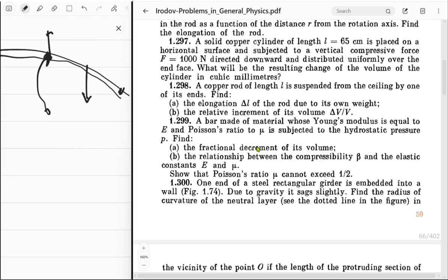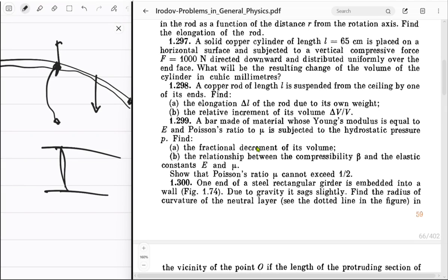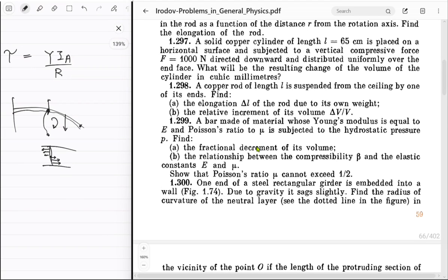The thing is, you have to think of it not as a single point, but as a cross section. So this is how it should be. I know this should be rotated, but think about it as rotating after you get the thing. So it's supposed to be rotated, but just do it. Okay, so this torque is in the clockwise sense. You want an anti-clockwise torque on this piece, right? The way this will actually work is that you will have these normal forces, which will add up to zero because no horizontal force is there, but they will create a torque about this point. Because of that, you will have cancellation of torques, and this won't rotate.